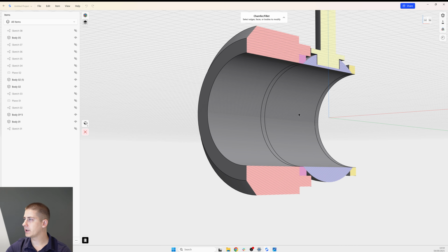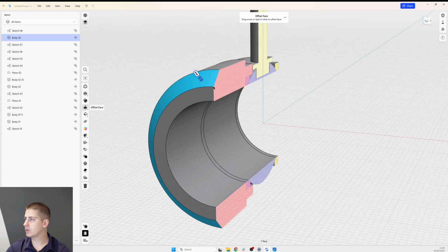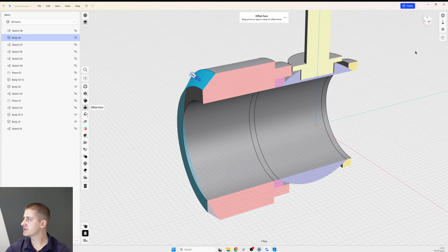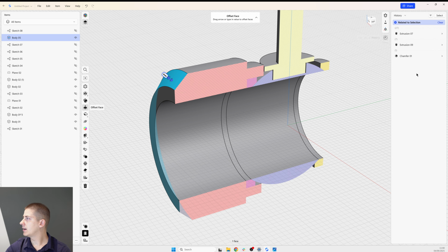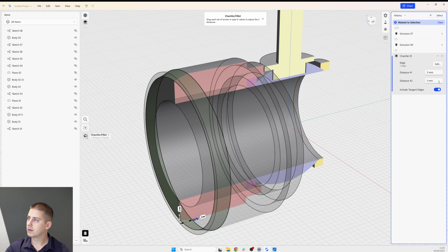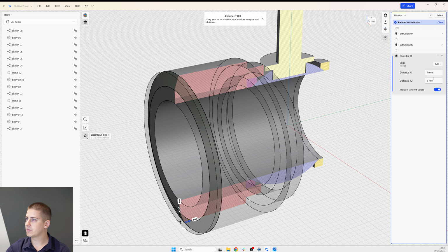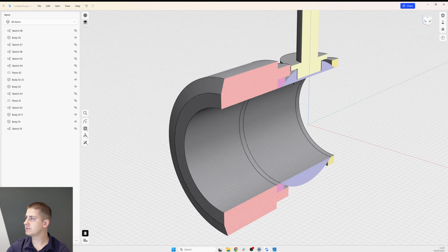And I would like it to be two distance chamfer, but now when I already created it with same distances, I want to find it in design tree, and here I can edit what would be the different values. So something like this is something I want to achieve.